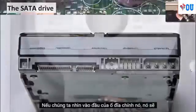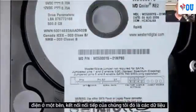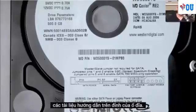If we were to look at the top of the drive itself, it would give us that documentation of what we just saw with the power on one side, our serial connection, which is the data connection to our motherboard, the jumpers that are on the side, and there's a legacy power connection built in right into the documentation on the top of the drive.